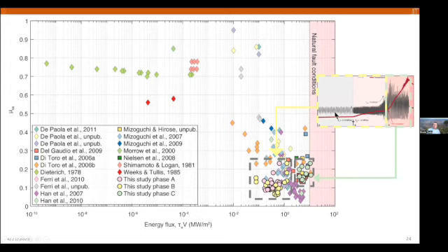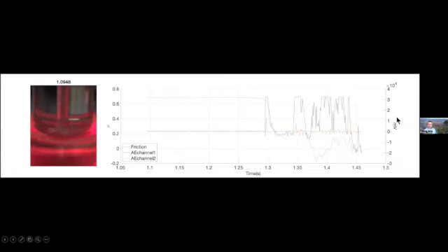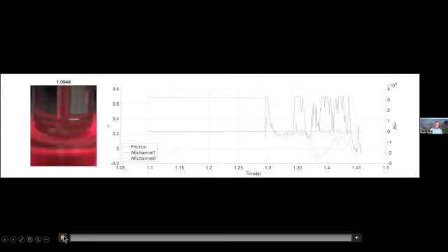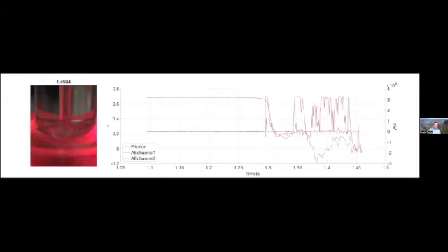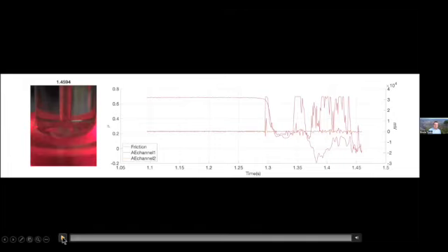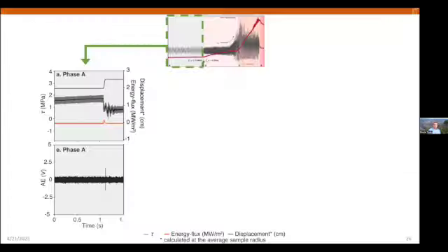And fundamentally, these are events taken from this phase, and these are experiments taken from this phase here. Okay, now I'm going to show you quickly a slip. So here is the friction coefficient, and then suddenly the friction coefficient goes down, and then the sample starts slipping. These are movies taken at 960 frames per second. So these are high-speed camera.